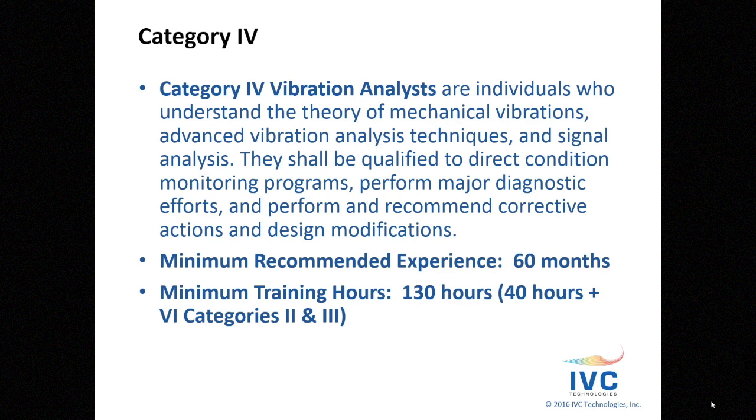The last category is Category 4, and this is primarily where you're going to be dealing with people that are consultants or specialists in the field of vibration. Category 4 vibration analysts are individuals who understand the theory of mechanical vibrations, advanced vibration analysis techniques, and signal analysis. They shall be qualified to direct condition monitoring programs, perform major diagnostic efforts, and perform and recommend corrective actions, as well as design modifications.